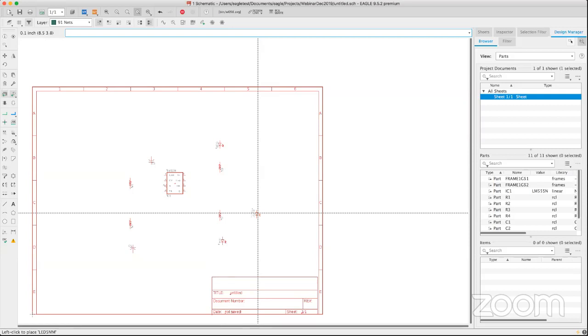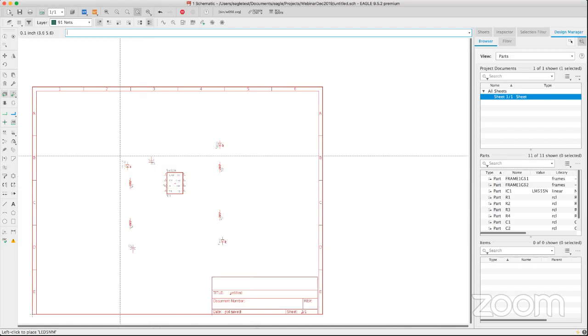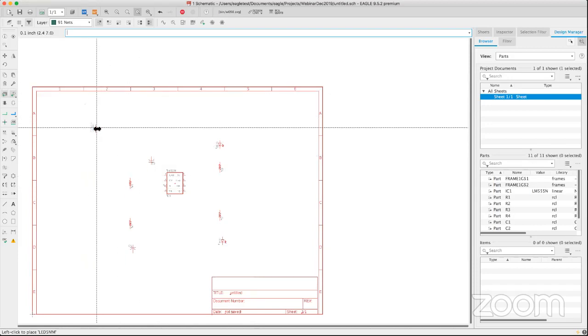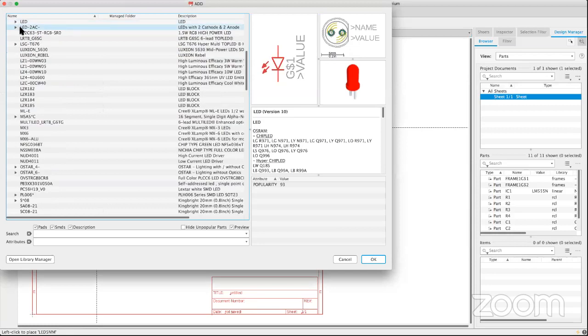Now, I'm going to be bringing in power into my design using a pin header. On earlier demonstrations, I was using a 9-volt battery. The problem is that when I work on the board layout editor, where the 9-volt battery sits on the board, it's kind of difficult to explain because it didn't make a lot of sense. So I'm just going to use a connector. That way you could actually have a 9-volt battery hooked up to a 2-pin connector and plug it into the design. So I'm just going to go ahead and hit escape, and I'm going to use my pin header library, which I already have enabled.